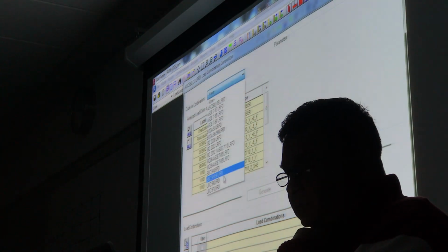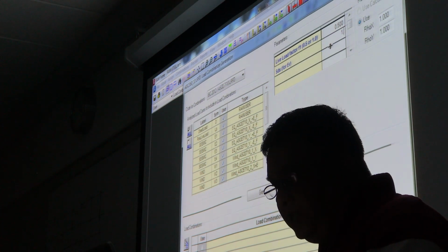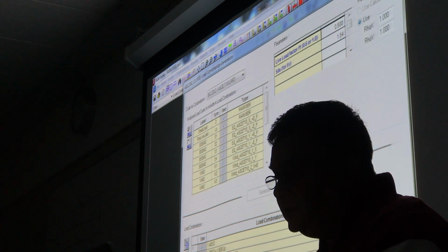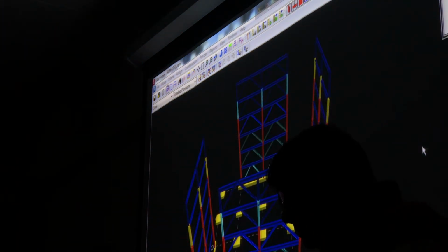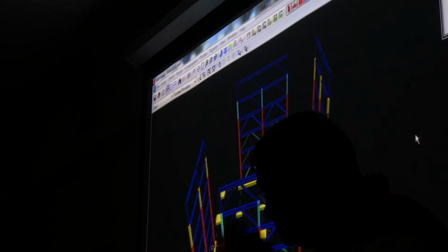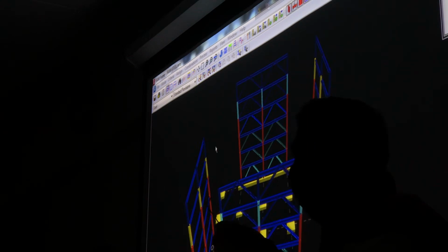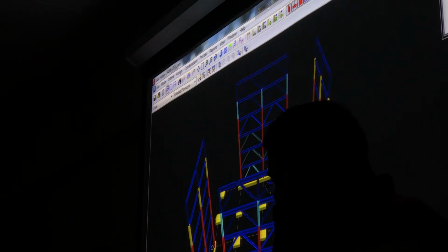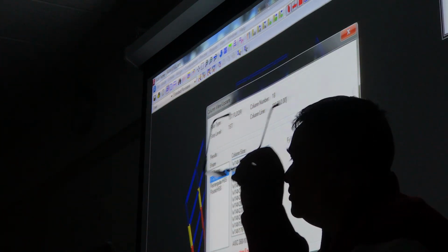which is called some additional checks for California, which is called standard provisions. Alright, yeah. Process member code check. Look at the columns. I pumped up to what, 14 by 390? Still doesn't work. Okay? Because we have fewer. Why it doesn't work? Let's check it. Interaction is 3.31. Way too much load.